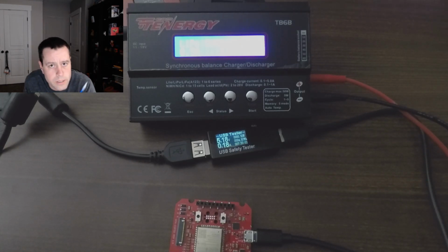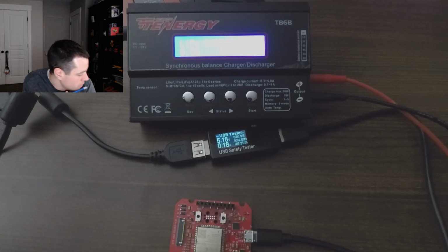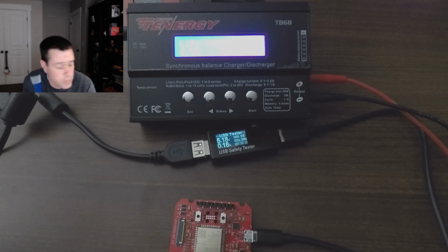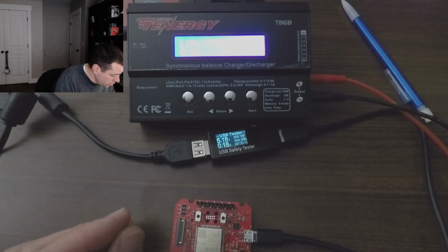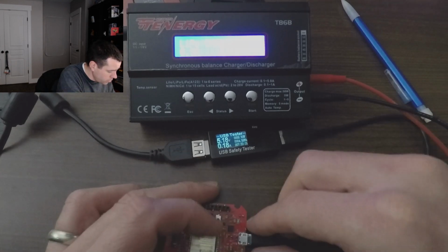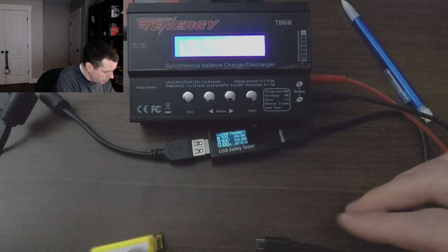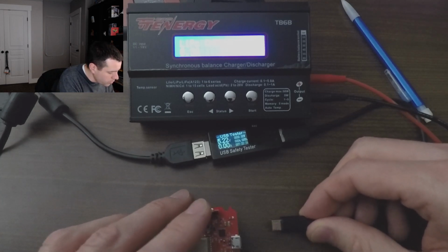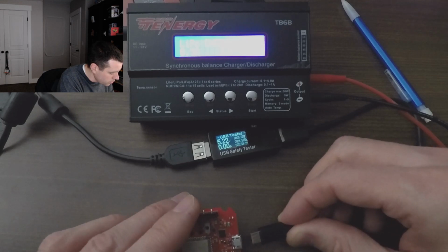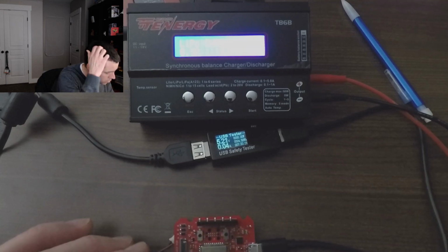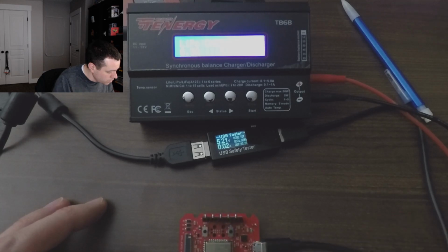So what I saw yesterday was probably a combination of me staying up too late and having the battery in a weird state of charge. Interesting. Okay. So that's what we'd expect. 180 milliamps. Great. I am curious though. Let's take the battery out. Yeah, it was 0.02, which would be 20 milliamps.